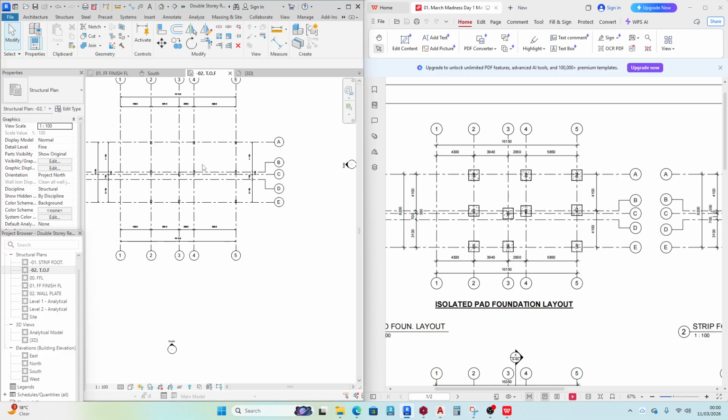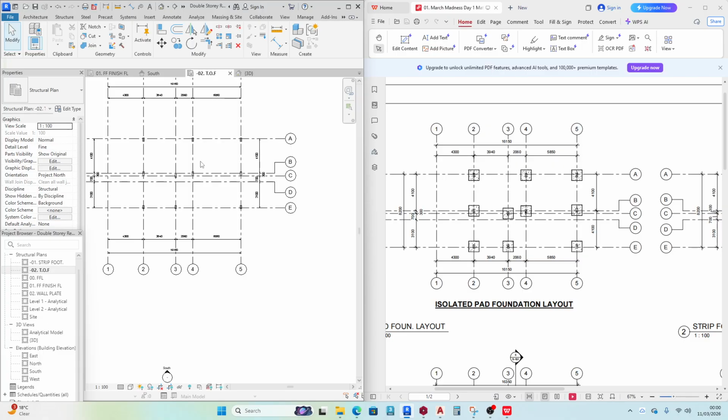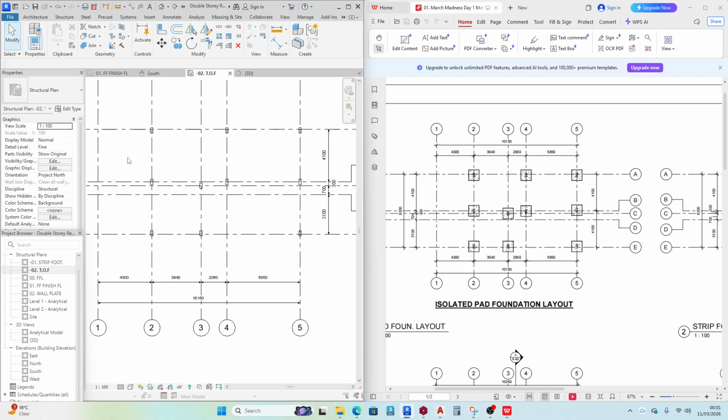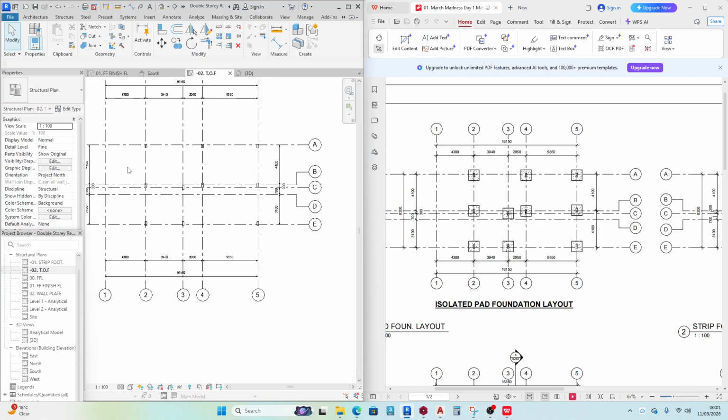And then we can add the proposed structural footings. So here we're proposing to use 1300 bases. So in fact, is it 1300? Let's try to use 1200. This is an assumption. We need to clarify. This is what structural design is about. We shall assume 1200, but then we'll go and run an analysis in both.